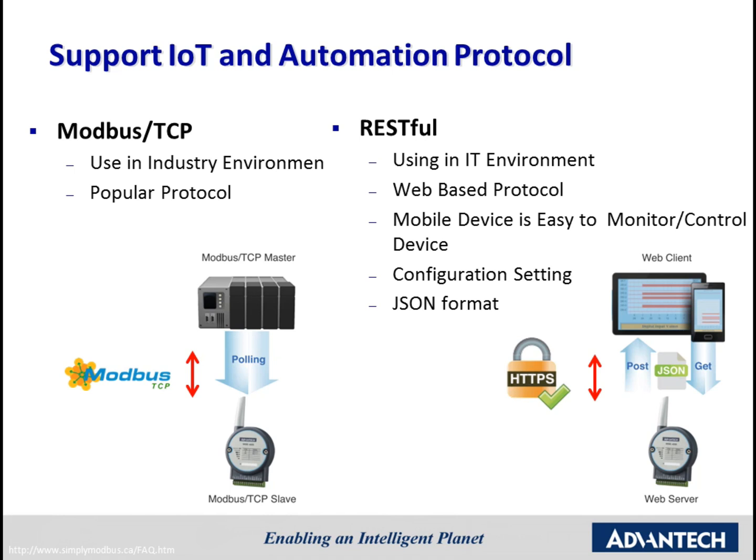Moreover, the biggest difference from Modbus protocol is that RESTful commands support all of the configuration settings of the WISE module. It is really convenient to change configuration in the HTTP environment and doesn't need any additional program to do it.